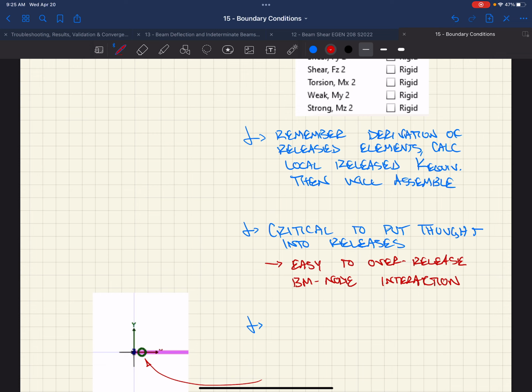What ends up happening in VA is, if you remember, you guys are in steel design, right? When you have sway and non-sway frames, when VA goes to design this column, it's going to figure out a K factor based on those charts, right? The stiffnesses of everything that's framing in, all of your columns and beams. So it affects your K value, whether this is a sway frame or a non-sway frame. You go 0 to 1, or 0 to infinity, or 10 to infinity, right? And so that's where that would play a role, whether or not this goes through.